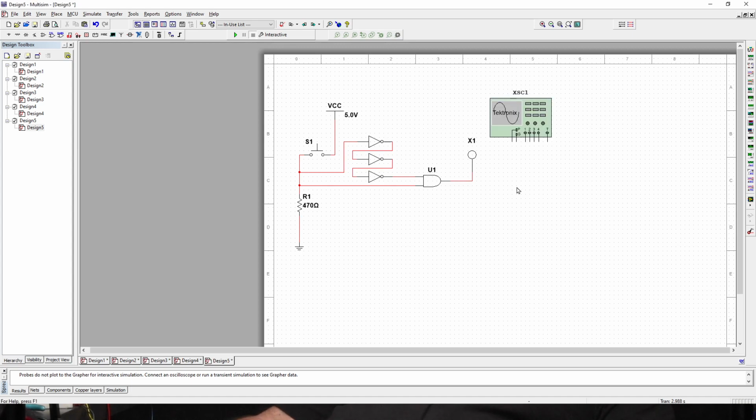Now, if we double click on that, we're going to get the whole oscilloscope picture, but let's just make some connections. Here's a ground connection, and I think there's the reference point here, but I'm going to have to confirm what this one, with the letter P, exactly is. Now here we have channels 1, 2, 3, and 4. It's a 4-channel oscilloscope, and here's a trigger input. We're going to use ground and channel 1 for now.